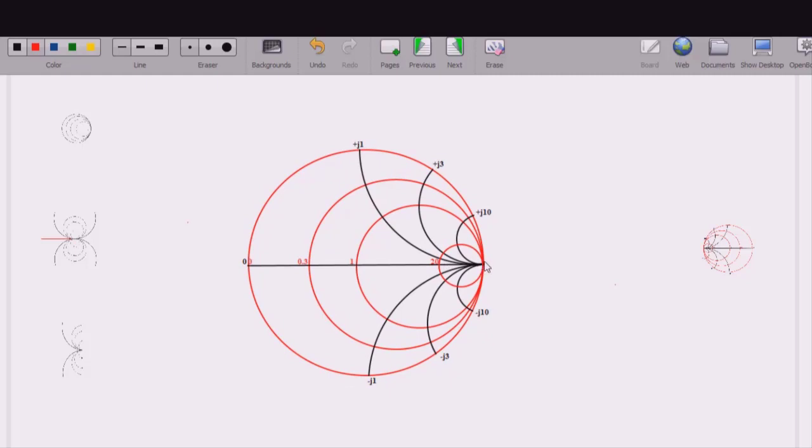Now instead of having complete perpendicular circles which represent reactances, only part of the curve is used from each circle. The reason is that, as I have already said, this outermost circle represents 0 resistance, and we are going to deal with resistance whose value is 0 to infinite.